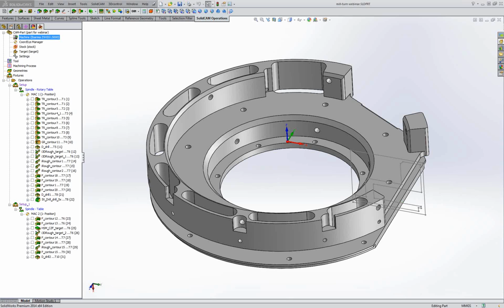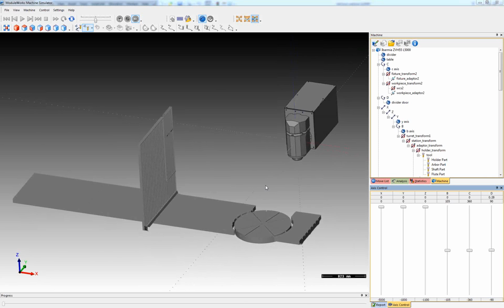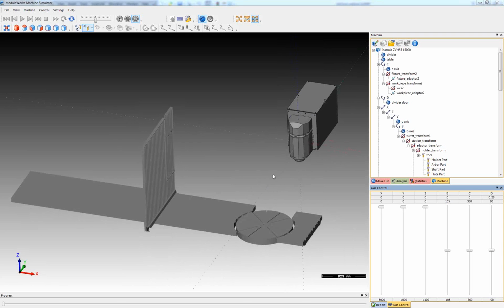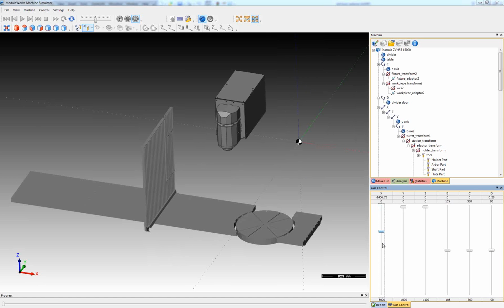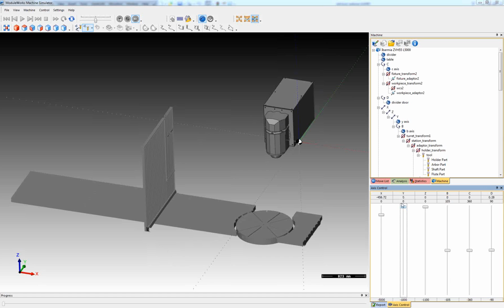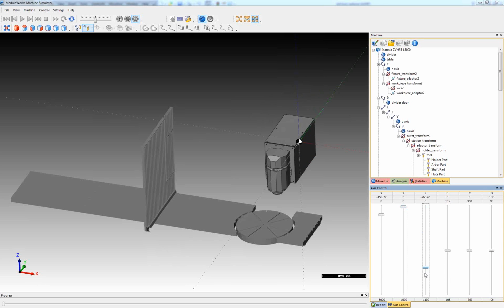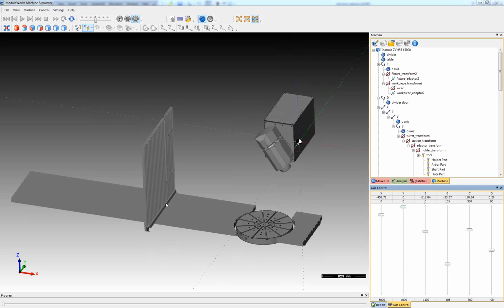So for today I selected an example. I have an Ibarmia machine from Spain, I think, with a very large table, a 5-meter table in X and Y axis. Also, all axes are on the turret: Z, and we have the B-axis, and the C-axis on the table. So what we have here is a milling table, a non-moving table, in combination with a rotary table. Here the manufacturer added the spinning option on this table, so it can be used as a 4th axis or as a turning table.